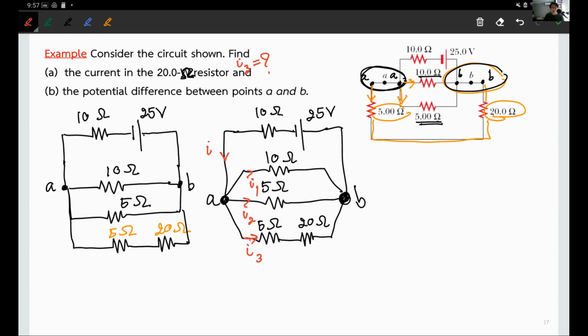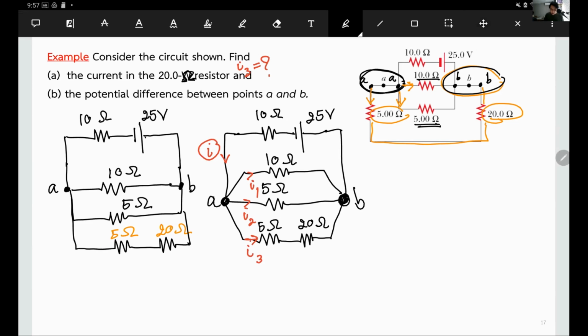So how to proceed, guys? Of course, before you can do anything else, you probably want to figure out what is the total current in your circuit first. Sounds cool? All right. So what I need to do is just reduce that crazy stuff here into a single equivalent resistor. So first of all, what you can see is in the bottom, these two are connected in series. So actually I can wrap this bottom into a single one if you like.